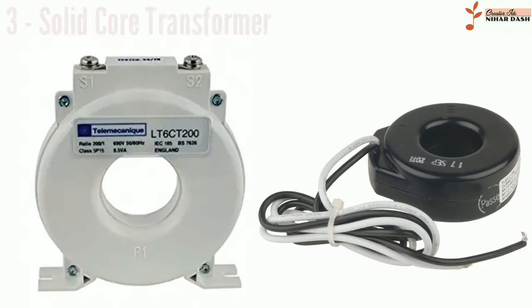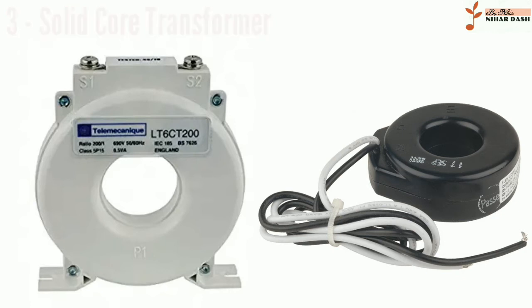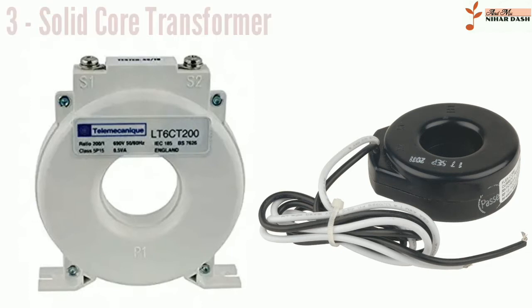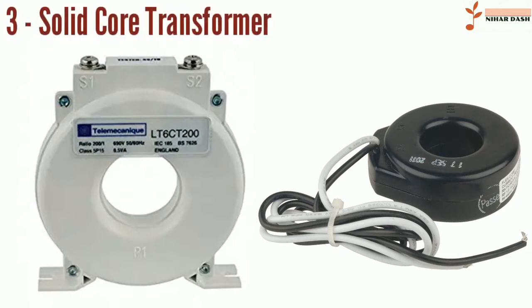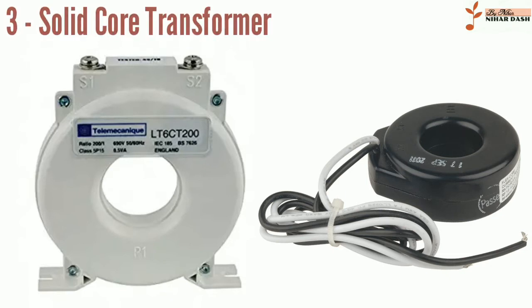Solid cores. Powdered iron cores are used in circuits such as switch-mode power supplies that operate above mains frequencies and up to a few tens of kilohertz. These materials combine high magnetic permeability with high bulk electrical resistivity. For frequencies extending beyond the VHF band, cores made from non-conductive magnetic ceramic materials called ferrites are common. Some radio frequency transformers also have movable cores, sometimes called slugs, which allow adjustment of the coupling coefficient and bandwidth of tuned radio frequency circuits.